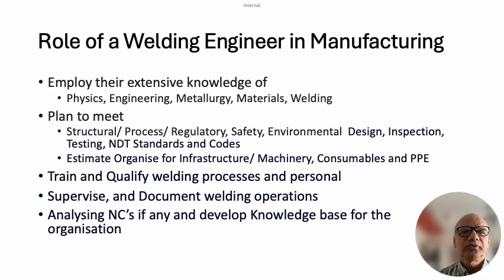Now let's see the role of a welding engineer in manufacturing. As we understand, welding is the most important process in any manufacturing, as it joins two parts together, and while joining these two parts together, we are going to heat and melt the material and bring them together with a welding consumable, which is another alloy, which could be a third alloy if the two parts which are getting joined are of the same material but may not be from the same heat or may not be from the same manufacturing process.